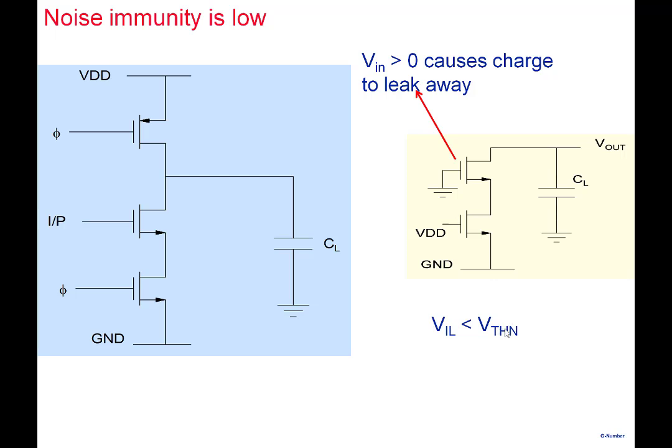So if it is 1 volt here, perhaps I can apply 0.8 or 0.7 or 0.6 at this particular value and still hope that this particular logic works properly here. In contrast, remember that in fully complementary CMOS, we were getting VIL close to 1.4, 1.45 or so. So we were getting a much better noise margin. So noise margin is going down because of this particular phenomenon here.